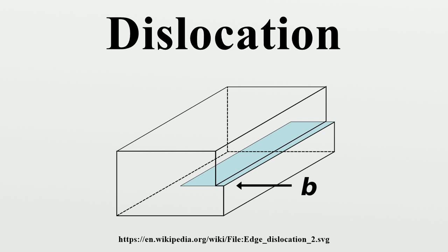This equation suggests a long cylinder of stress radiating outward from the cylinder and decreasing with distance. Please note: this simple model results in an infinite value for the core of the dislocation at r equals 0, and so it is only valid for stresses outside of the core of the dislocation.